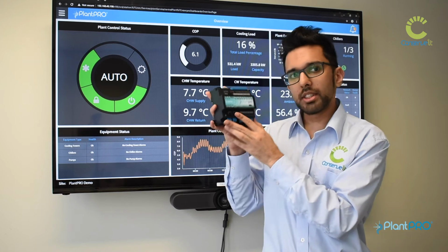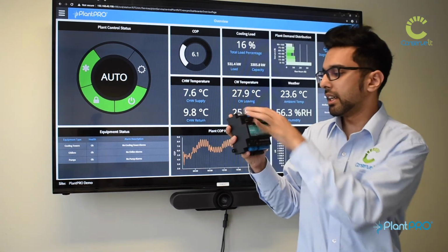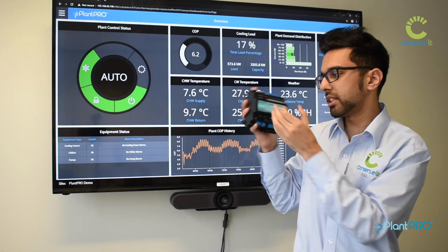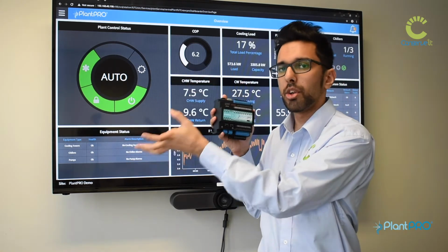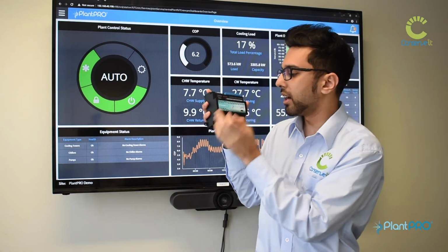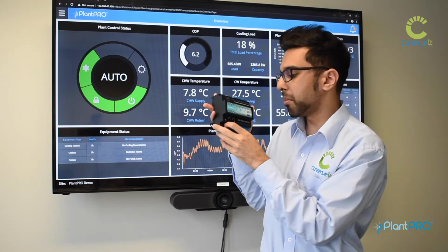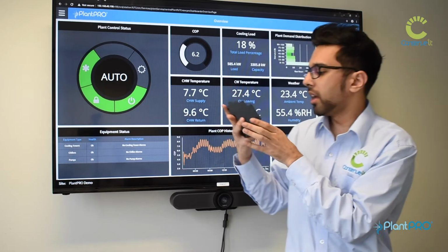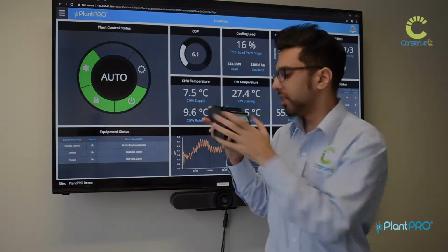And one of the other advantages of using the CI534 is the small form factor. As you can see, it has the I/O points on it. And even though size-wise it's similar to the DZ3000, it doesn't need an additional I/O module. Also, if you're going to be using a serial protocol like Modbus RTU or BACnet MSTP, you can directly communicate with the CI534 using the serial port, whereas with the DZ3000 you will be needing to use an additional module.